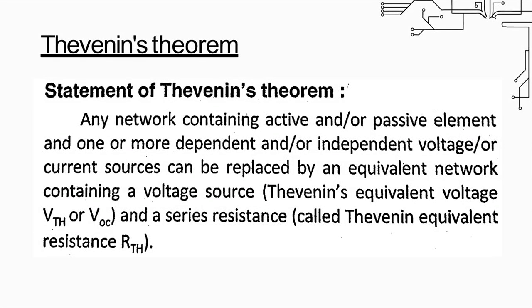म्हणजे Thevenin's theorem मध्ये आपण बघणार होतो की ज्या ब्रँचच्या अक्रॉस आपल्याला करंट कॅल्क्युलेट करायचा आहे त्याच्यासाठी आपण त्या ब्रँचला रिप्लेस करत होतो किंवा त्या ब्रँचला आपण ओपन सर्किट व्होल्टेज VOC किंवा Thevenin's equivalent व्होल्टेज म्हणतो आपण त्याला VTH, तो आणि एक सिरीज रेजिस्टन्स ज्याला आपण Thevenin's रेजिस्टन्स RTH म्हणत होतो, तो आपण त्या रेजिस्टन्सला कनेक्ट करत होतो आणि मग आपण करंट फाइंड आउट करत होतो using Thevenin's theorem.